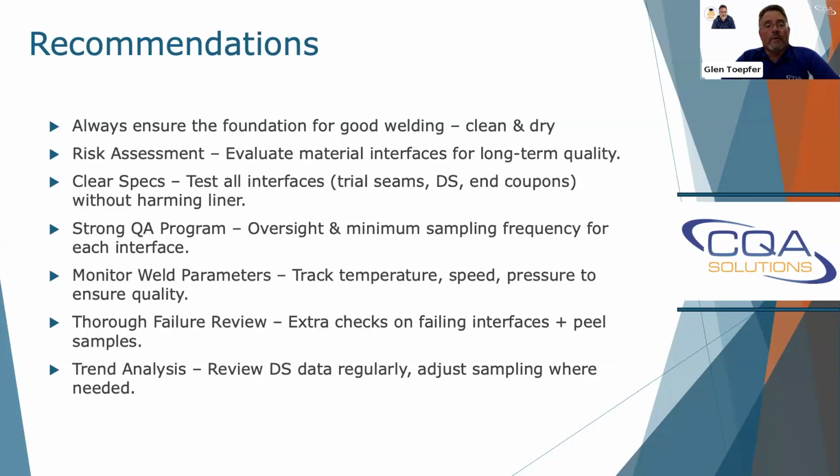Monitoring the weld parameters, obviously the temperature, speed, pressure, needs to be done. You need competent CQA. That's one thing I left out about the failure rates. We at CQAS often have higher failure rates than other people because we do it differently. We do the interval, we try and use it to the best of everybody's advantage, help us learn from it, ensure the quality while we're doing it, and not create more holes in the geomembrane.